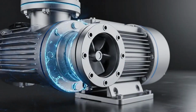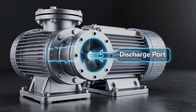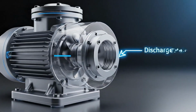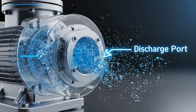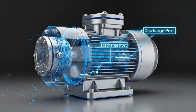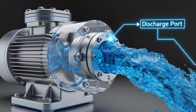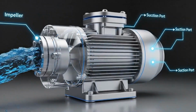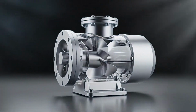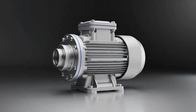We see the discharge port. The fluid leaves the impeller and is guided through the volute, exiting the pump under pressure. The impeller draws the fluid into the suction port, accelerating it radially before it is forcefully expelled through the discharge port. Together, the casing, suction port, and discharge port form the primary external structure, directing the flow of liquids.